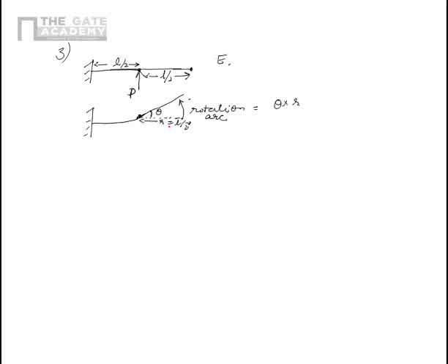Now you see, we have to get the deflection here and add this portion to get a total deflection at this point. What is the deflection here? We can get it very easily from the previous case, which is, we know that the deflection at, let's say this point is A, at A is equal to P by 3EI multiplied by the length till that point, which is L by 2 cube. So I get this PL cube by 8 multiplied by 3 is 24EI.